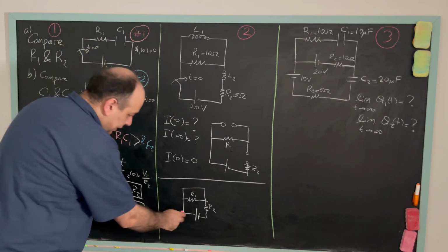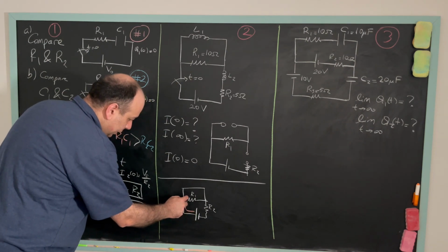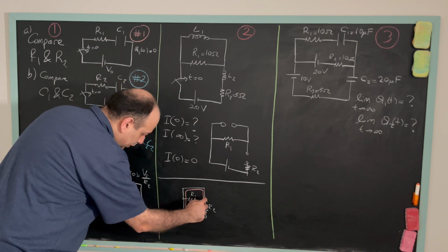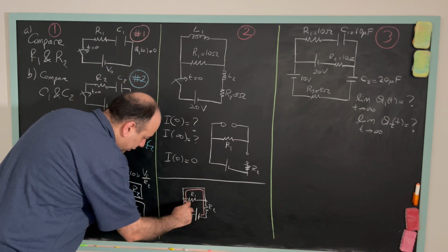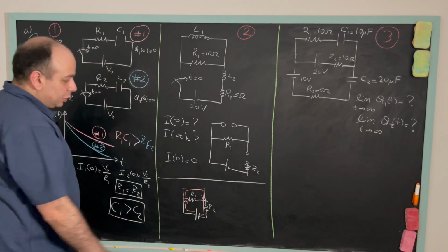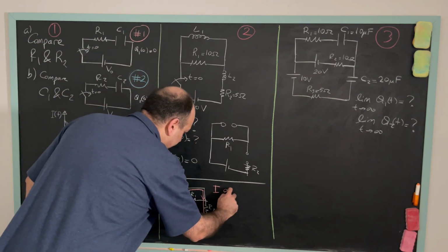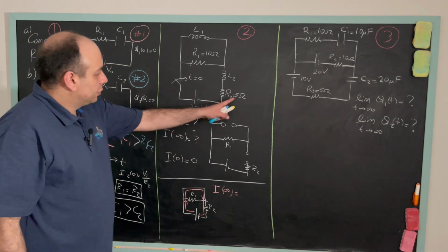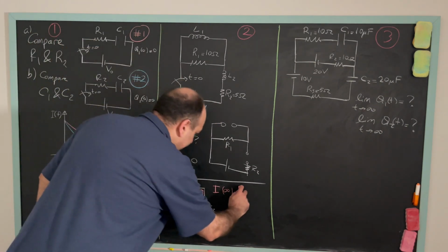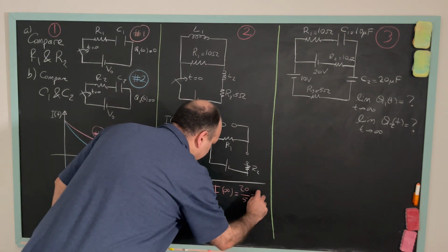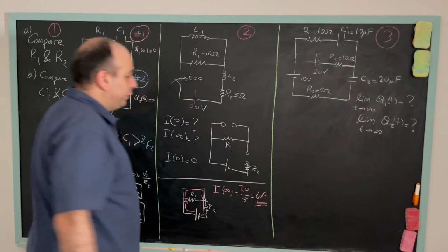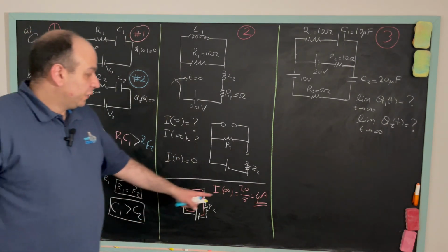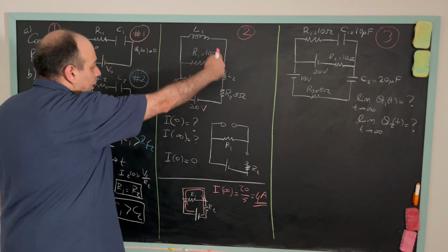As you see, we have a short circuit here, so the current is going to run through like that. It's going to bypass R1 and run through R2 only. So this will be the direction of the current. When time goes to infinity, we will only have R2 in the circuit. So 5 ohms, 20 volts: 20 divided by 5 is simply equal to 4 amps. If you wait long enough, the main branch current here would be just 4 amps, and it's going to go through R2 only.